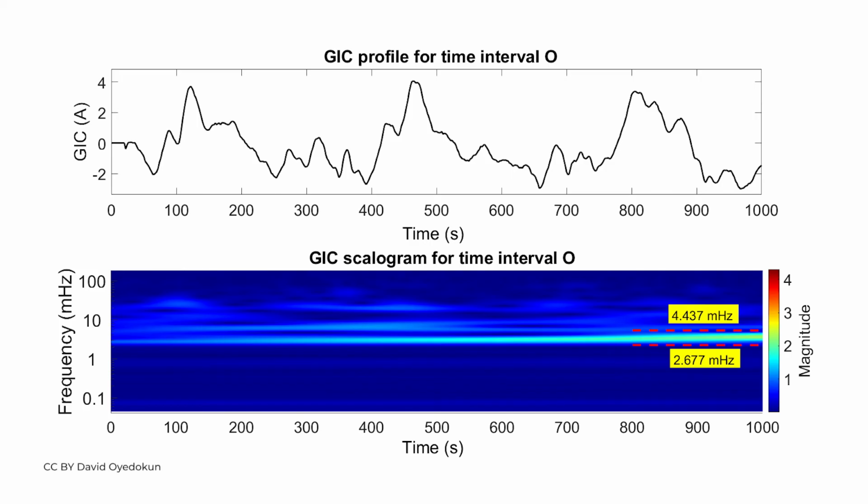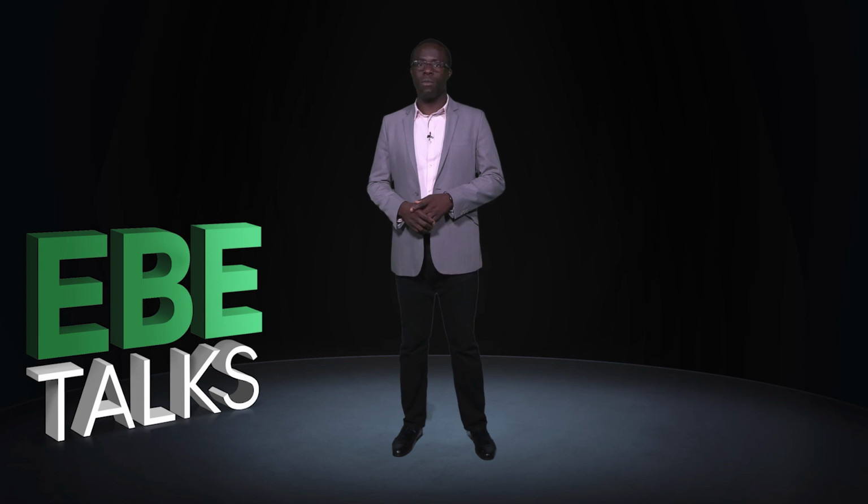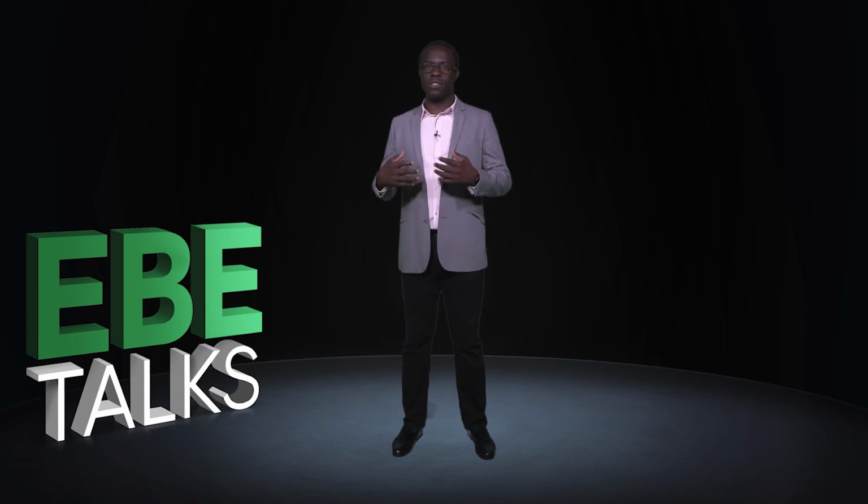The signal processing techniques proposed and used in this study can be used to identify the trend in GIC. We know that dynamic time domain simulations are important, and they provide information about the critical network nodes and the nodes expected to have high voltage drops. Using such information for contingency planning may provide more useful control measures required from system operators to mitigate the dangers from geomagnetic storms.